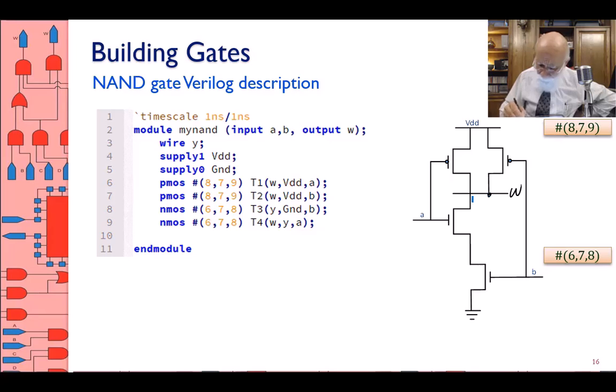And okay, I have to write one transistor at a time. It doesn't matter which one I write first. The lower ones, the upper ones, however I want to arrange them, I can arrange them. It doesn't make a bit of difference if you write PMOSs first or NMOSs first. I'm emphasizing this because the description you see on the left hand side is a concurrent description. That means inside the module, you have a concurrent part, so the order of the statements does not matter.